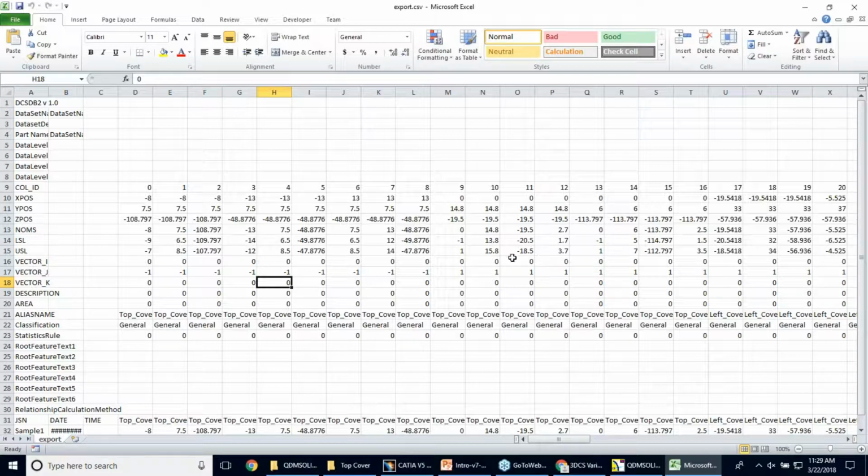And that's one of the reasons why QDM is so useful here, because it's a pass-through for 3DCS to connect to all of those quality programs in production, so that your 3DCS user can then use measurement data found in production for root cause analysis, problem solving, and continuous improvement. Right, so not only is this an export for the CMM machine, it's an export that can possibly be brought back into the model. Just to summarize that a little bit.